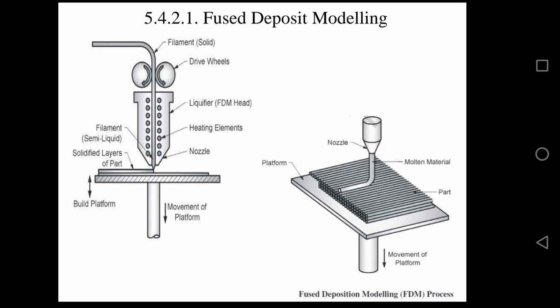So the material solidifies within a very short period of time once after extrusion, and it cold welds to the earlier layer. The movable nozzle is of dual tip actually. One nozzle tip for producing the part geometry, and another nozzle tip for producing the support structure.